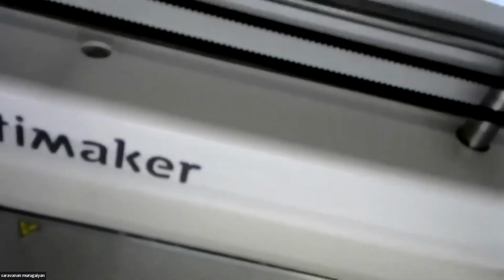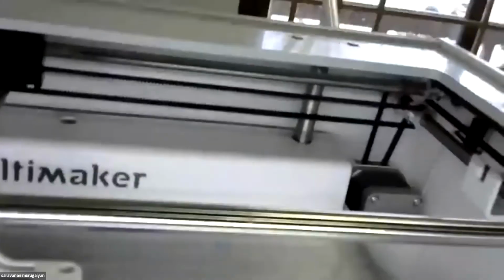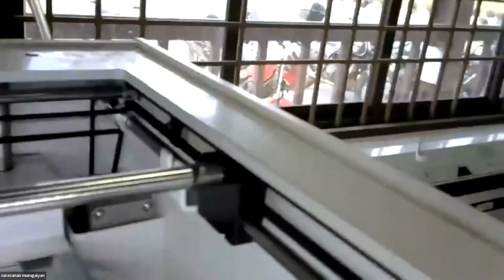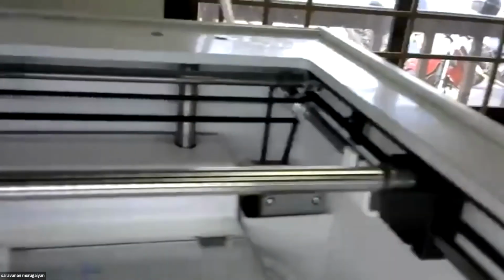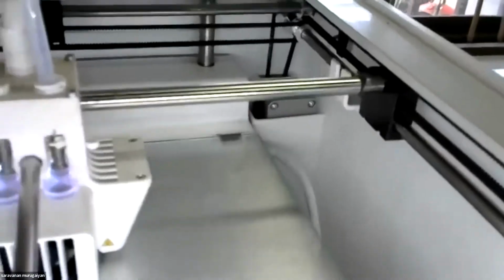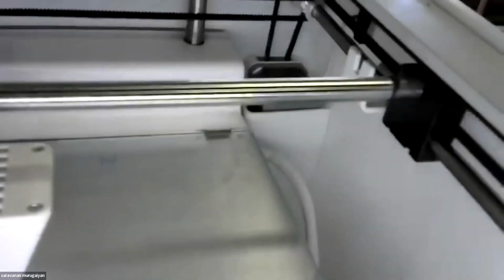This geared rod is in turn connected to the ends of the actuator of the extruder. So the rotation of the stepper motor is directly converted into linear actuation of the extruder with the help of the belt setup in the machine. The rotation of the motor moves the belt, and the belt in turn moves the extruder, which positions it at the proper coordinate position given in the G code data. This is how it works.